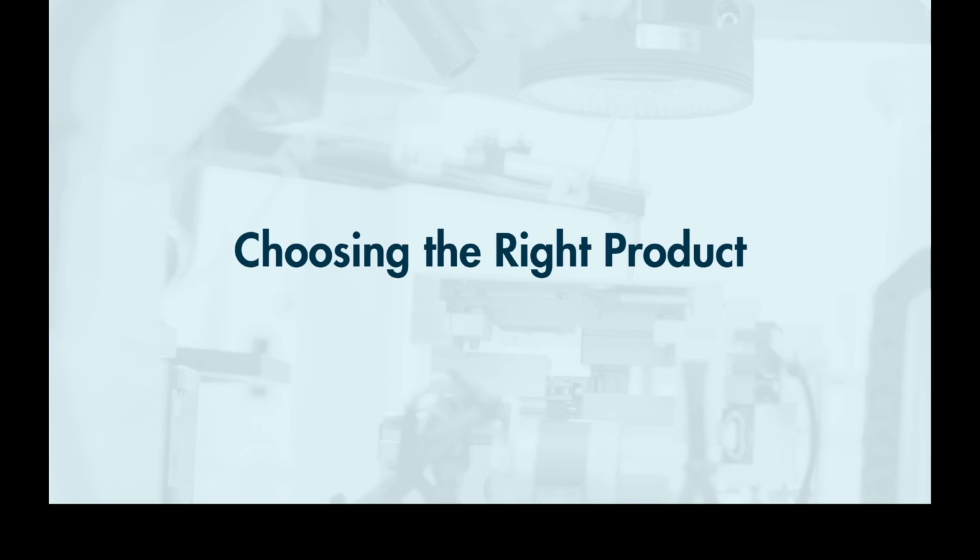So that's actually it when it comes to line scan lights. Because they are essentially just bar lights with the one line of your camera that you're inspecting, there's not that much you can really do with it besides changing the uniformity or coaxial dome, that kind of stuff. But it's not like area scan, where you can have square, big, small, lots of different options that you have to consider. So there's not as many line scan lights as there are area scan lights, and we can still solve most or all of the applications.